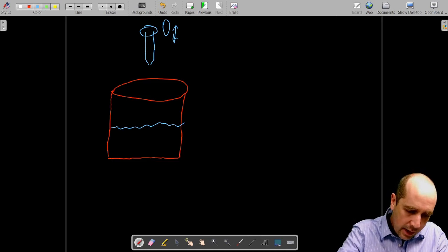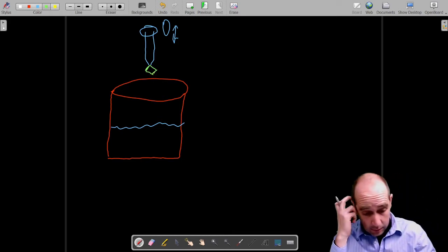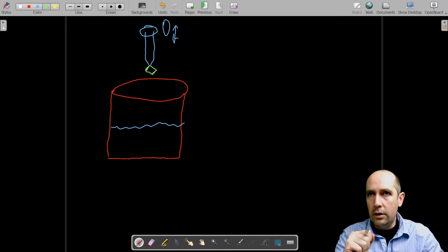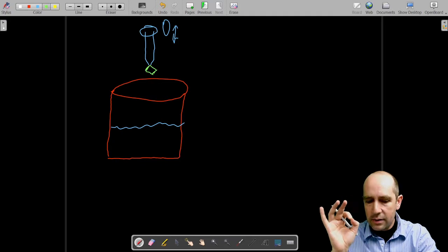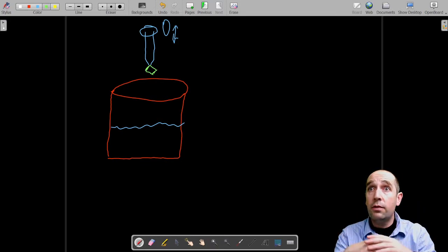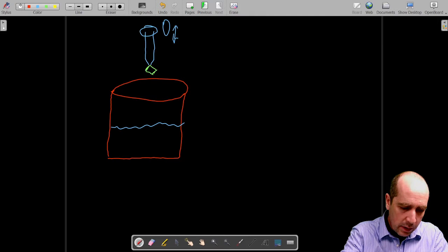Okay, the next step is that in this rod we put what we call a seed, and a seed is crystalline silicon. So it's a small piece of crystalline silicon, something like a grain of salt, or maybe a little bit bigger, but it's a relatively small piece of very high purity, very good quality, single crystal silicon. Okay, and I will try to make a drawing here.